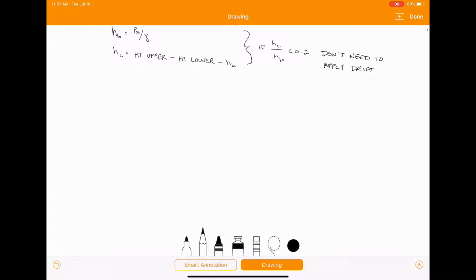So then we've got HD, which is determined from figure 7.6-1. Now, you can plug values directly into that figure, or just below it there's an equation. I like to just plug everything into the equation because you get more of an exact number rather than just eyeballing something.